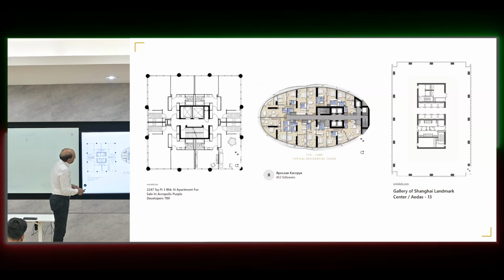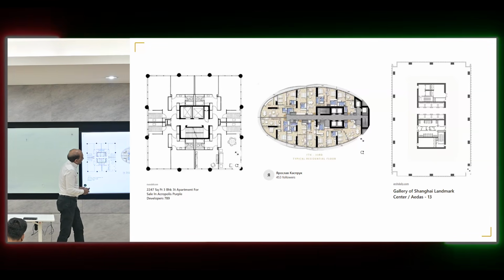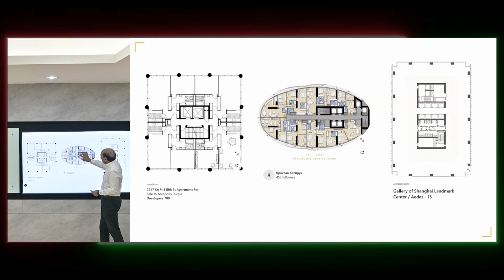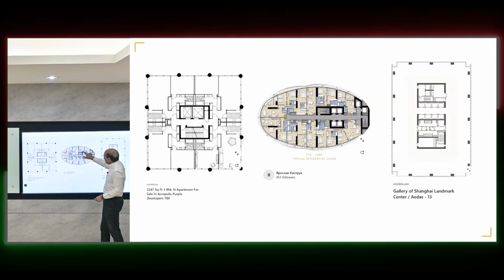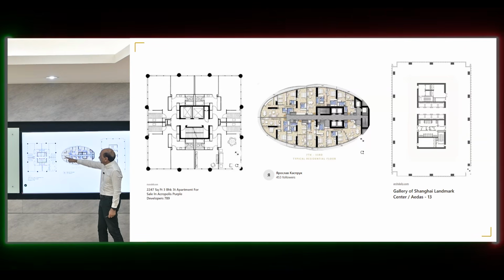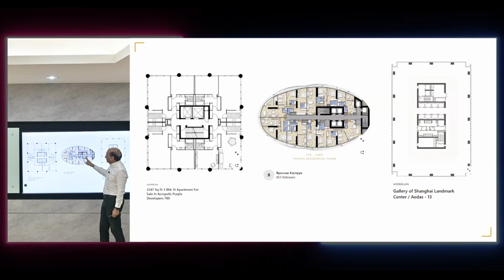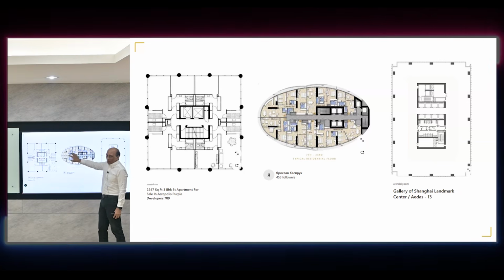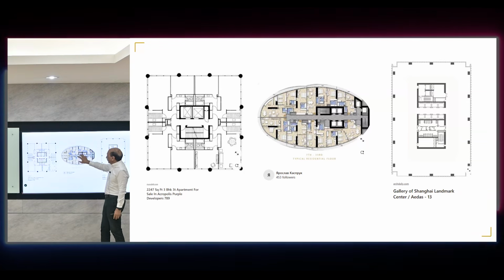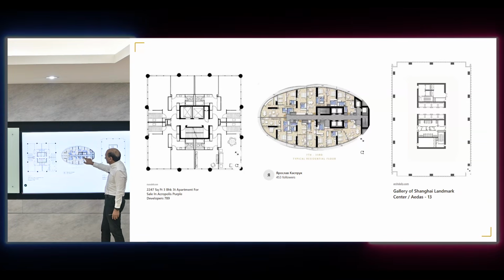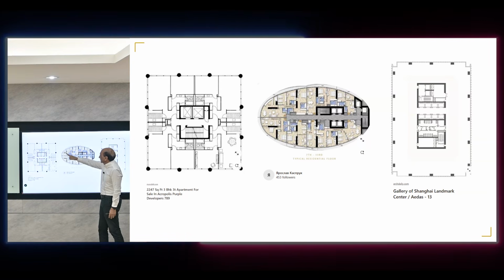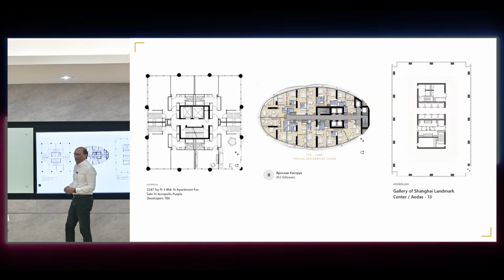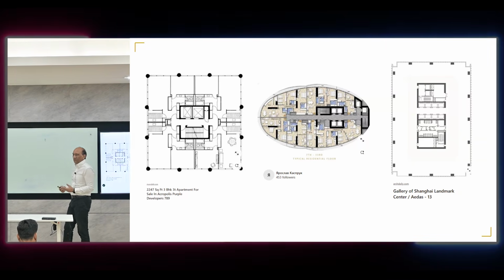These are some other buildings with the core. Now some buildings, like this one, the core is off-centered, and it's not big enough. So you need more shear walls. So the structural part of the wall is then distributed, not only at one location. Because the core is too small, you add more of these black parts that you see. These are the structural shear walls, in addition to the core, when the core is not sufficient.